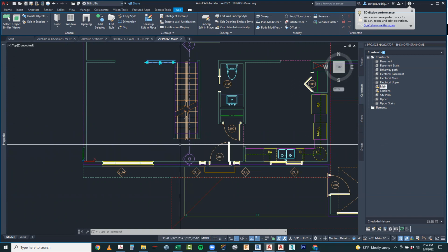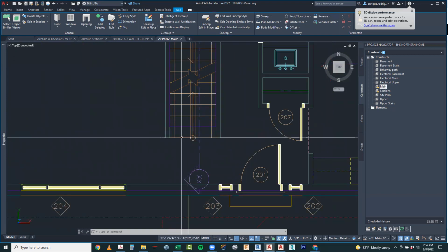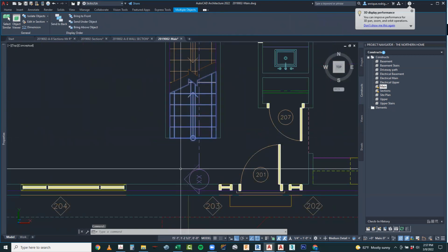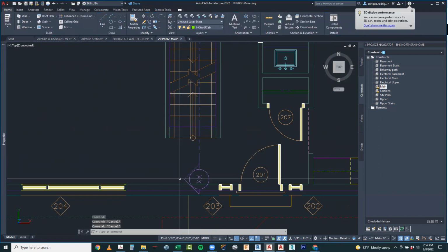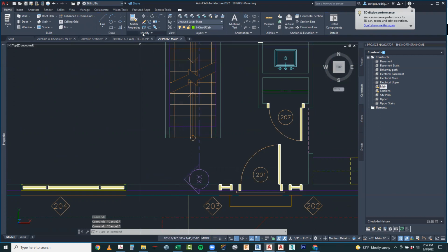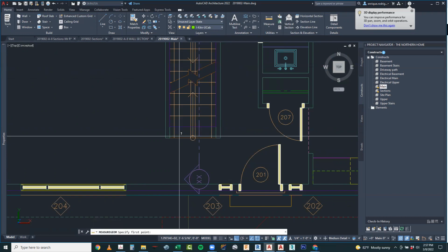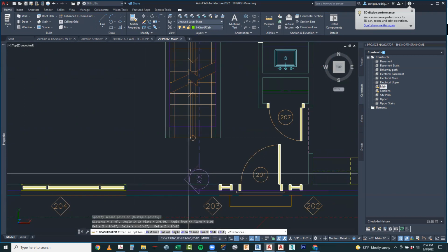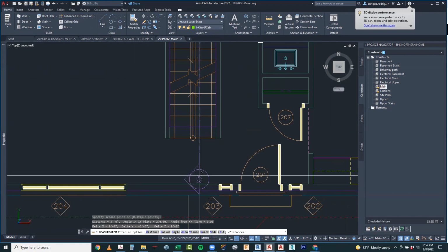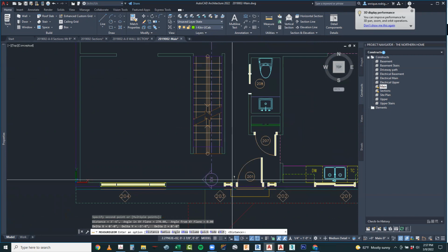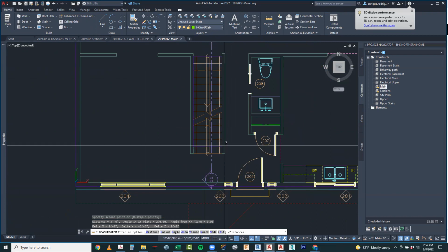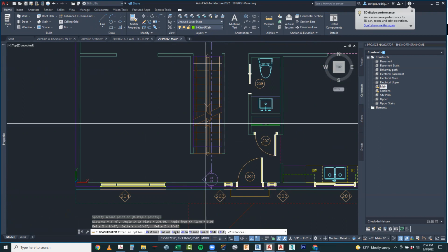The other thing that's extremely important is, well, how much space we have at the landing of the stair on the floor. Ideally, we want a minimum of 3 feet. If I was to take a measurement right now from here to the wall on the main, we have a measurement of 3 foot 6 inches. So we're more than okay at that point. But the problem is that is not our most critical horizontal run.